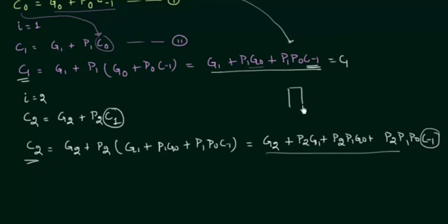So what we are actually doing is saving some time. And how it is done, let me show you. This is your C minus 1 directly fed to your first half adder. These are your two numbers A, B, definitely the first bit of the two numbers, and then you have the sum, and after all these things you have your carry. So if I want the carry from this adder, I have to wait all the way until this adder has given the value, and then only do I have the carry here from this adder. So we have to wait for some time because the gates inside this adder will take time.